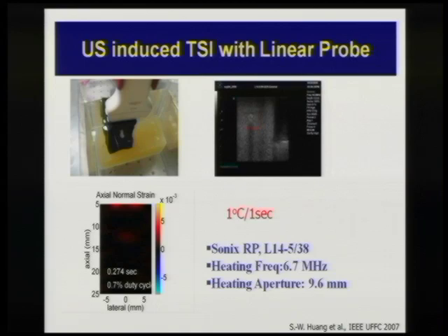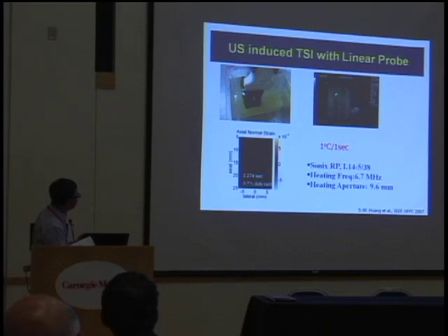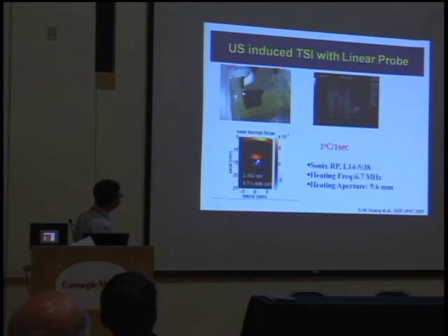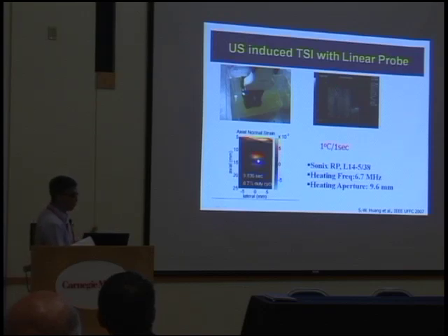Also, to demonstrate the feasibility, can we do this on a commercial ultrasound transducer, we used Sonix Touch, and we coded our heating pulse and imaging pulse into it. There is a phantom with an inclusion of rubber, just for the proof of concept. As we increase the temperature, we were able to detect this lipid surrounded by gelatin phantom, just to demonstrate that we can apply this technology to a commercial scanner.